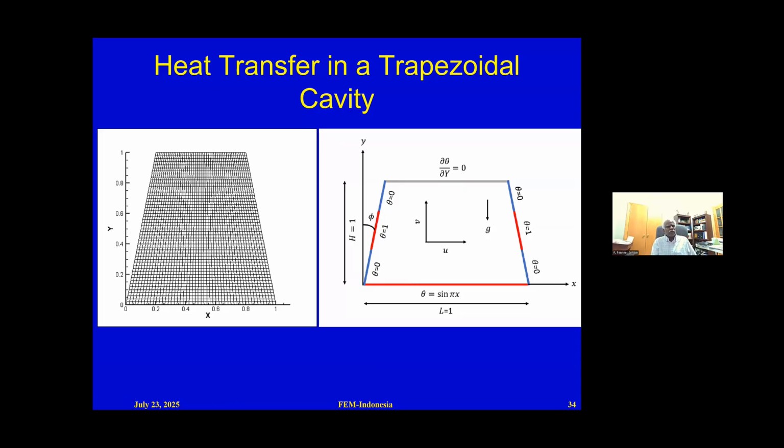So we used quadrilateral elements, solving for temperature, because the temperature differences are what drive the velocities. Then velocity and pressure are each solved continuously by the finite element method, because of the somewhat complex geometry. For this geometry, one could also use finite difference or control volume, but implementing boundary conditions and other things is very elegant using finite element. So we chose finite element because we also want to do much more complex geometries in the future.